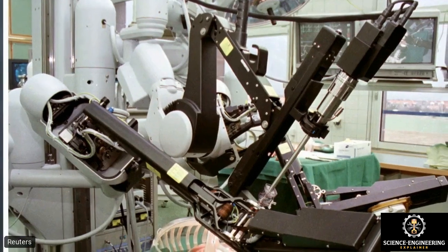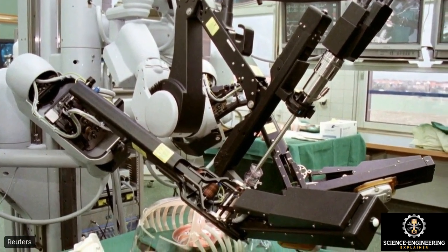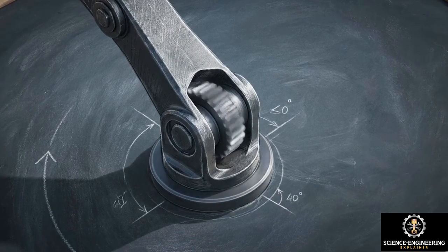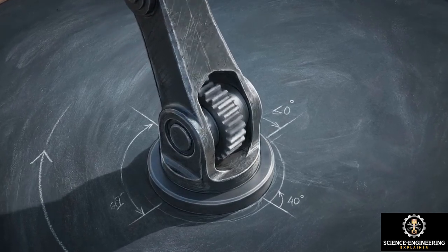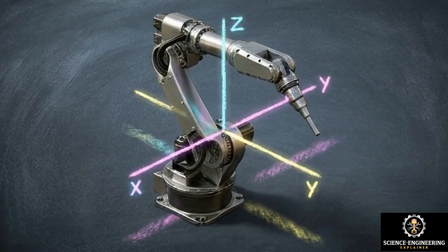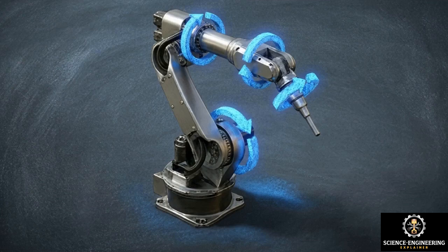The math is perfectly planned, but physical motors cannot process Cartesian spatial poses. They only understand individual joint angles. We have to translate our idealized spatial path into actionable hardware commands. This requires differential kinematics. We need a mechanism to convert the Cartesian trajectory, operating in the SE3 matrix space, into precise localized velocities for every independent joint on the robot.